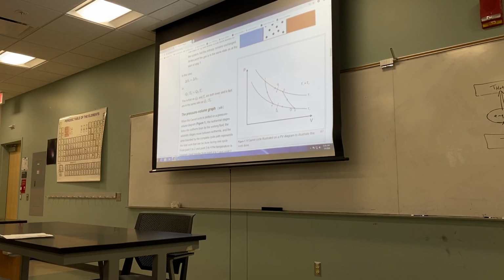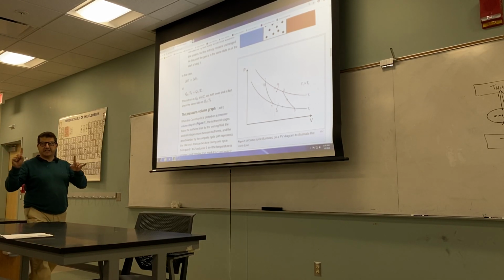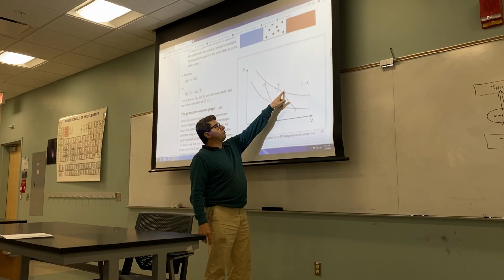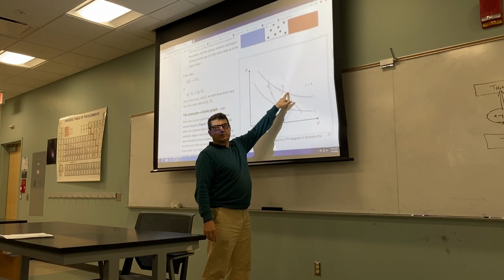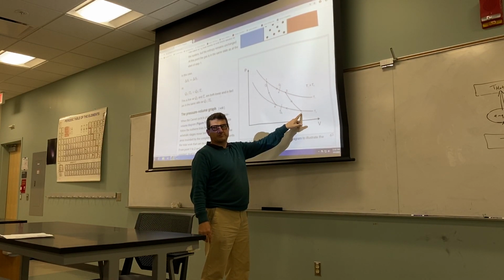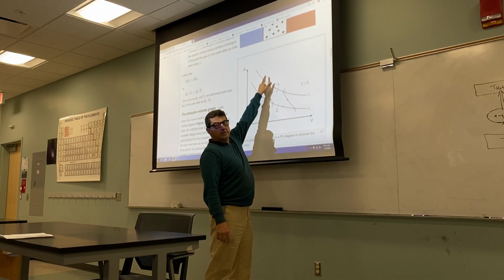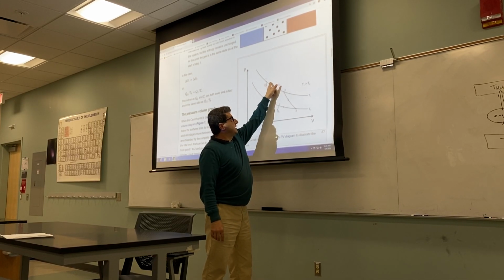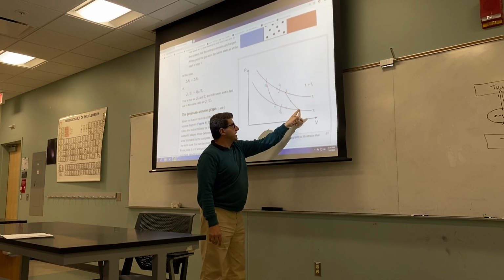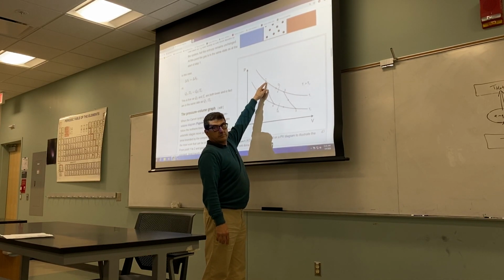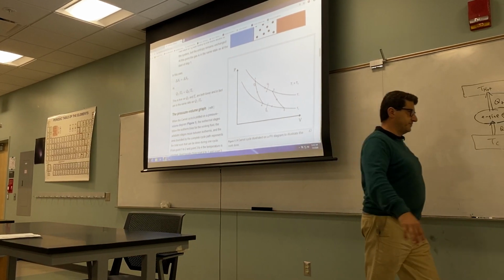You could start anywhere, but it starts here. It goes isothermal, adiabatic, isothermal, adiabatic. Remember, in adiabatic you go from one isotherm down to a different isotherm. Then you stay on that isotherm, then you go adiabatic. So it's isothermal, adiabatic, isothermal, adiabatic. That's the Carnot engine.